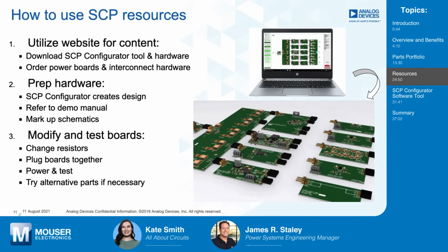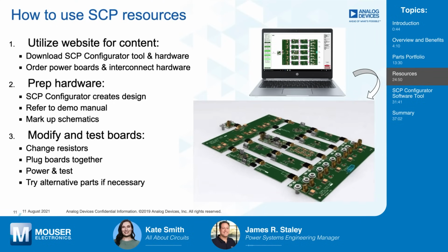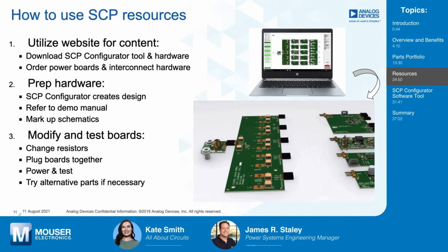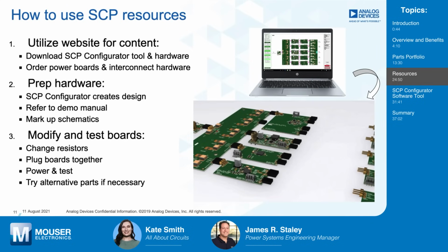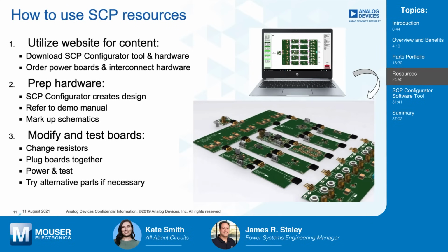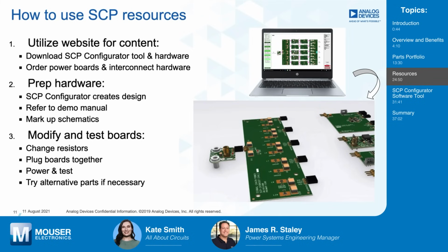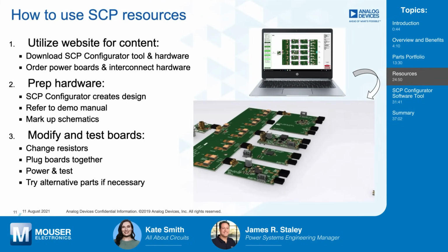As a matter of fact, it was one of the design requirements. We actually oversized the resistors that were most likely to be changed, such as the frequency setting resistors and the feedback resistors and some compensation components. Those were left intentionally in 0805 size resistors when they could have been made 0402, just to ease and facilitate changing those parts out frequently.